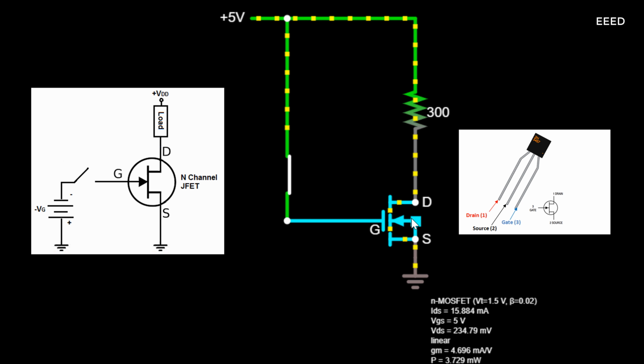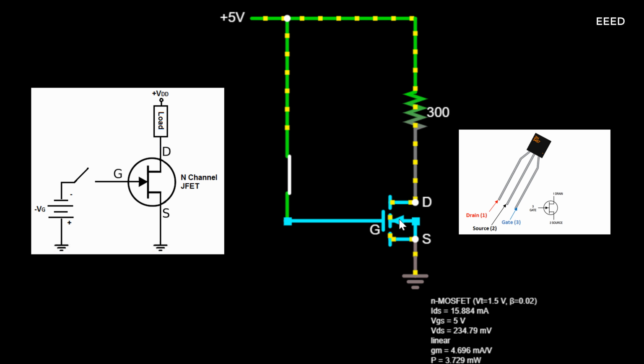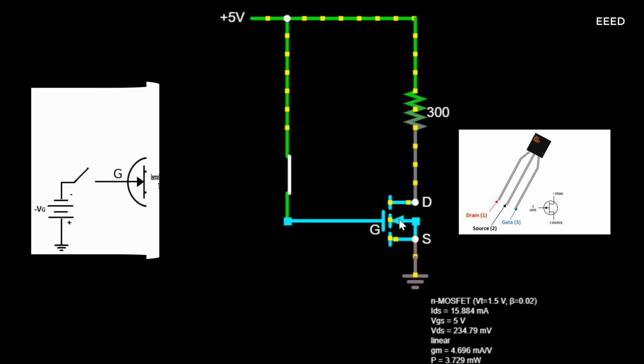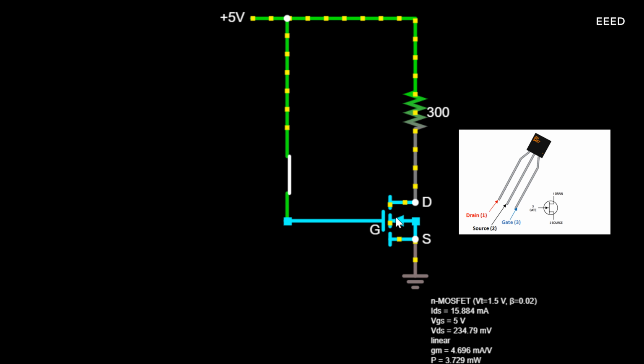When a negative voltage is applied to the gate, the drain current is reduced. As the gate voltage, VG, becomes more negative, the current lessens until cut off, which is when the JFET is in the off region. Characteristics curve of an N-channel JFET.